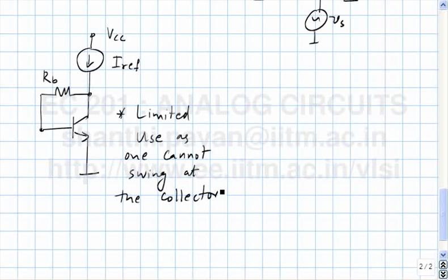What is the next bias technique that we saw in the MOS case? The next bias technique was to measure the source current and tweak the source node. So the corresponding bipolar equivalent will be to fix the bias of the base at some fixed value, compare the emitter current with the reference current and go and kick the emitter itself, and that leads us to this bias technique.